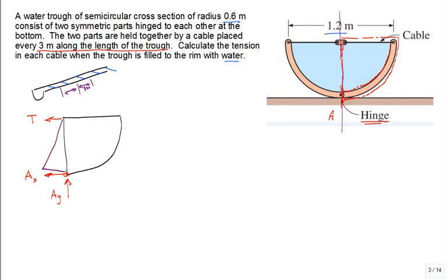It's a hydrostatic pressure. And so we're going to replace that distributed hydrostatic pressure with the single equivalent force, which will be probably like that at that location. We'll call it F_R. We can calculate the magnitude of F_R and the location where F_R should be applied. Why not go ahead and do that right now?